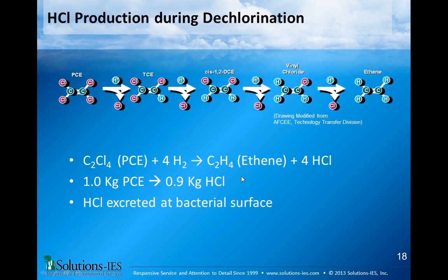And worse yet, it was fairly clear that substrate was not getting to the contaminant. And in fact, there were probably some permeability changes. It might have been due to biomass. It might have been due to gas bubbles. But the water was sort of flowing around the contaminant, not through it. If it flows around, it doesn't dissolve. You don't get degradation.